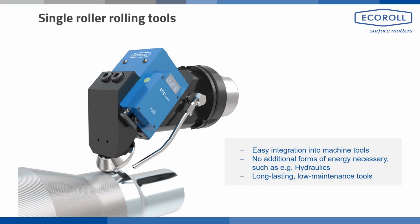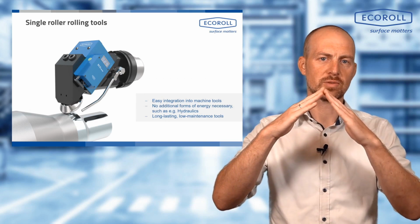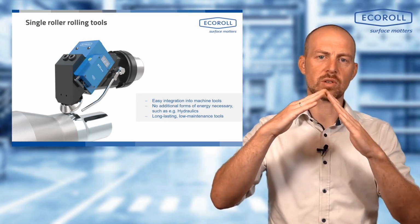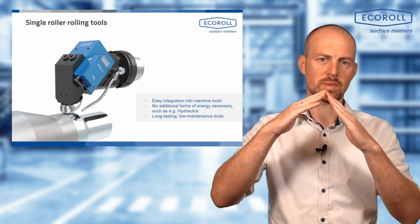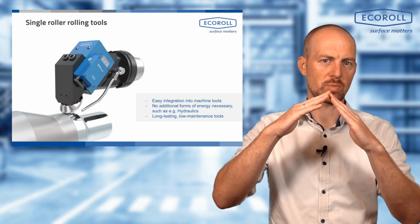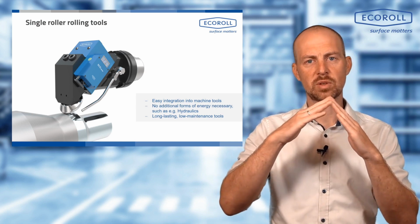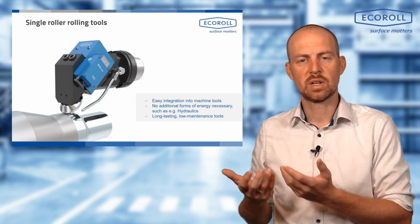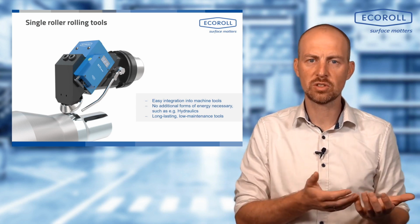There are leaf spring packages positioned at 90 degrees to the rolling cylinder. This orientation allows for a deflection of the rolling cylinder when I bring my tool into collision with my component. That means I essentially position my roll. I drive into the component and simultaneously guide the leaf springs out. This deflection of the leaf springs then defines the rolling force. This is also what we measure with our measuring gauges.